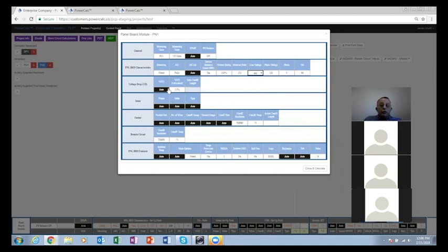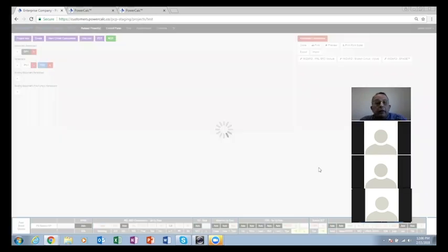Then you go through all these ribbons, and to adjust the number of poles, you go to the panel features and say this panel is going to have 42 spaces, and then close and calculate. It's going to open 42 spaces for you on that particular panel.